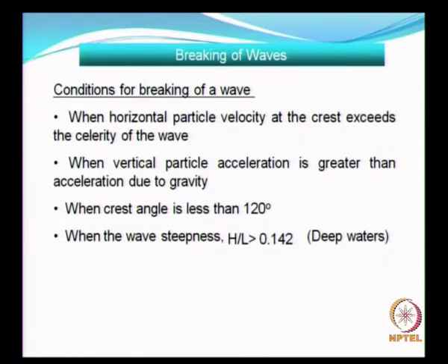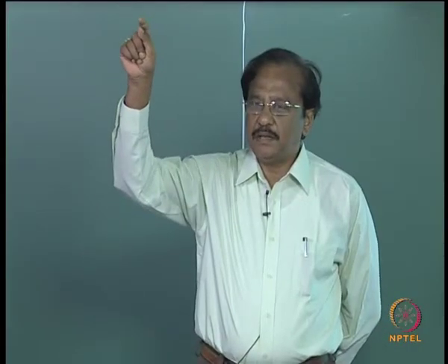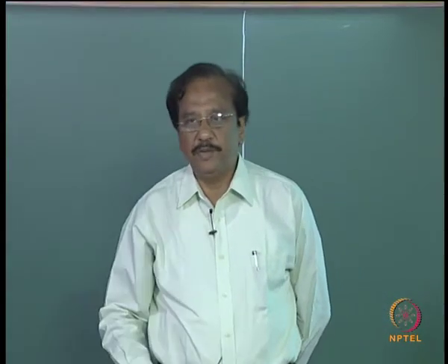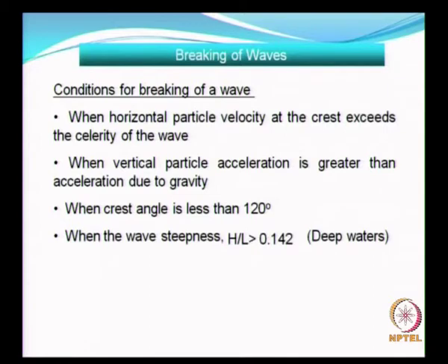That is, the velocity corresponding to the crest of the wave, when that velocity exceeds the celerity, the speed of the wave, when the vertical particle acceleration is greater than acceleration due to gravity, when the crest angle is less than 120 degrees. That is another criteria.